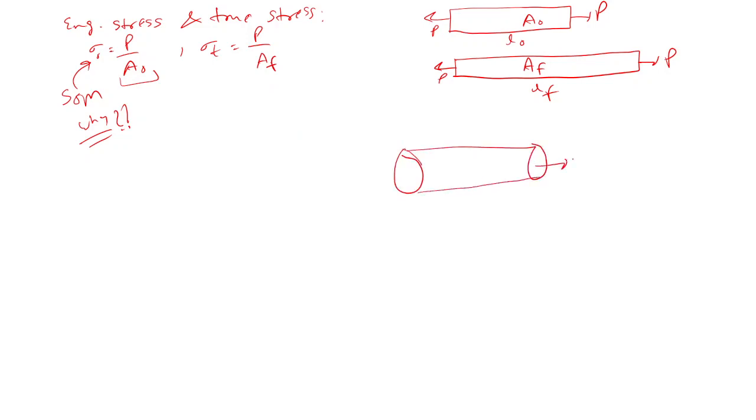and this diameter is 80 initially, and the final diameter when load is applied will become 79. So there is a 1 mm change in the dimension. But if we take the true stress, the calculation would be very difficult, because at any instant the diameter keeps changing. To monitor that is very difficult, and the calculation would also be very tough. And the error is also not much, because if the deflection you get from 80 is 2.44 mm, let's suppose, with 79 you will get 2.42. So that is not that much difference.